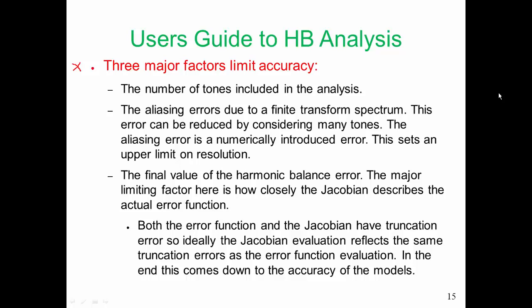And some of you will end up having to develop your own models. If you're trying to do a competitive design, there is a chance that you're going to be using transistors that no one else has used. And since it takes 2-3 years to develop a transistor model, very often you're going to be dealing with situations where the model has not been developed by others. Your company, your organization has a competitive advantage by getting in there first. And there are companies that you can also contract to develop models. So lots of decisions need to be made there. But in the end, we go to the lab. Any errors here we can fix sometimes in the lab.